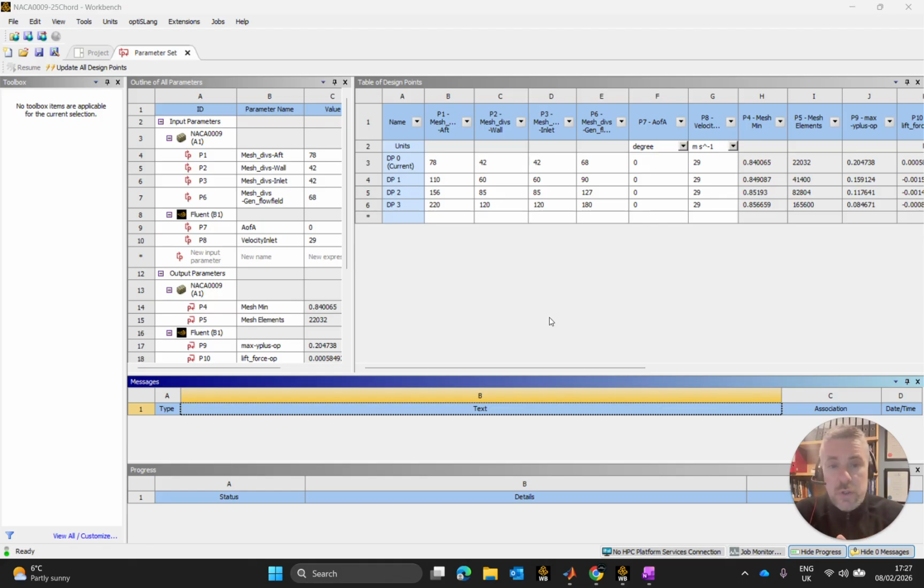So in the last video we finished off the grid convergence index study and we determined that the grid as laid out in design point 3, or this level of refinement, has returned one in which we are most confident that the discretization error within our discretized flow domain is at a level that we can live with. So our GCI value was adequately low and our apparent order was still at a value that we could be relatively confident with, that numerical inflation or any sort of artificial inflation hadn't taken too much of a major effect in it.